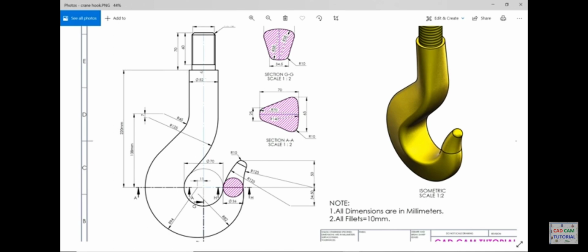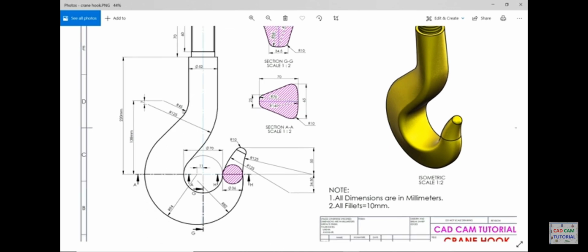We will define. Start from here. This diameter 52, then we will create this path. Just note down the dimensions: 45 from here to here, center distance 138, then there is this curve 125 and 7 millimeter gap between these two curve points, 220 millimeter from here to center, then this is 94 millimeter, this is 82, and this distance 75, 35, 75